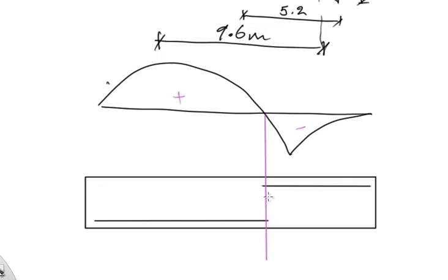To be honest, I cannot think of another way for now, but there is the long way and there is the short way, and each way has its own advantages and disadvantages. The short way is the one I just showed you, going through the problem very quickly, finding the reactions, finding the shear, and drawing the moment diagram, and understanding that at a certain point,